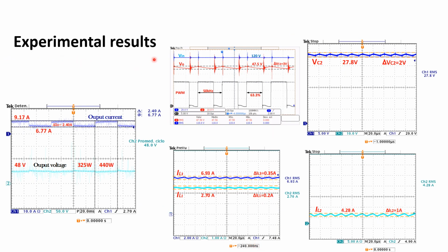After completing the mathematical analysis and controller design, experimental tests were conducted where the system's waveforms were obtained at different operating points. This includes the transformation ratio, buffer voltage, input and output currents, inductor currents, and the load variation. This allows us to observe the regulation capacity of the Type 3 compensator.